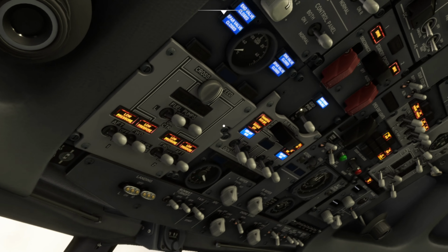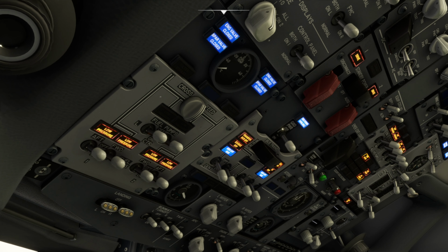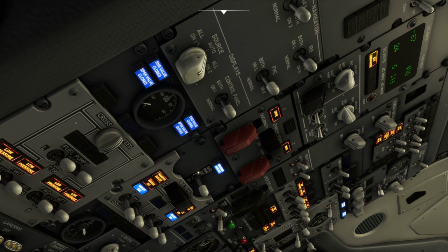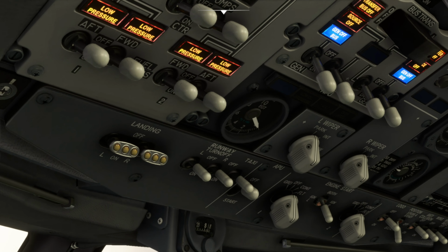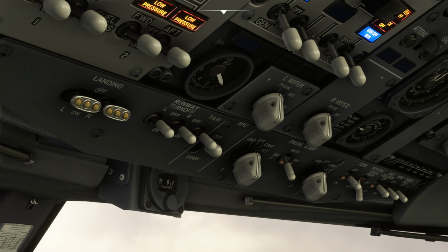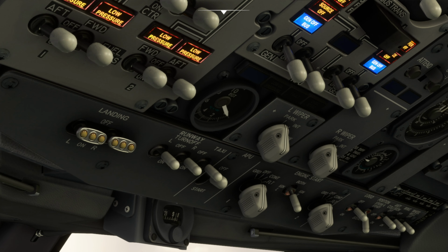First thing we need to do, because we're on battery power here, and we may get caution warning here to show that we are discharging our DC bus, DC obviously coming from battery power, we will need to operate the auxiliary power unit. We'll see this gauge here, roughly center of screen. That is showing exhaust gas temperature from that gas turbine engine mounted in the tail that we took a look at the exhaust ports of earlier. That's the auxiliary power unit, and it will generate hydraulic pressure and electrical power for the aircraft.